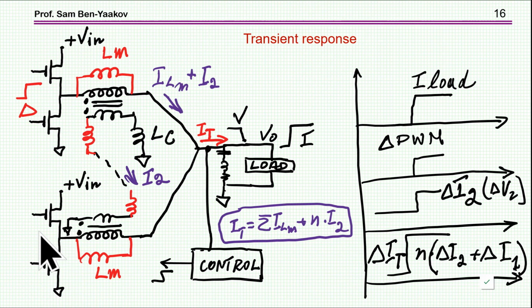Now there are different ways to go here, and I'm assuming now, at this first example, that this change, at this particular instant of this transient, is affecting only one half bridge. Okay, this operational half bridge at that time is affected, and therefore it's now getting an extra high level of a drive here, extra of what is supposed to be. So we have here the load, we have here this extra voltage, the drive here.